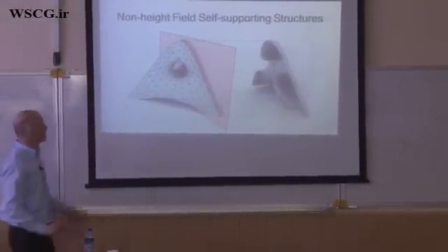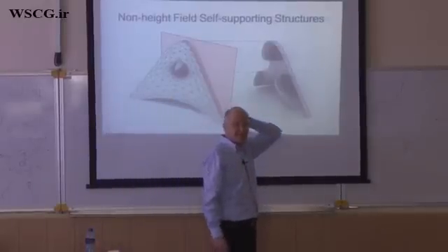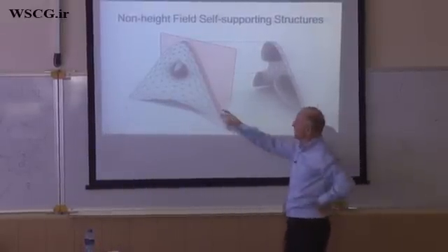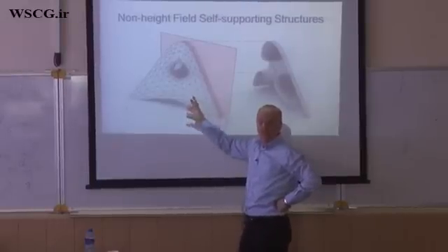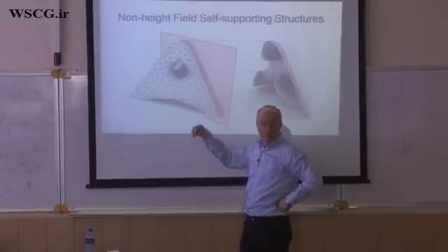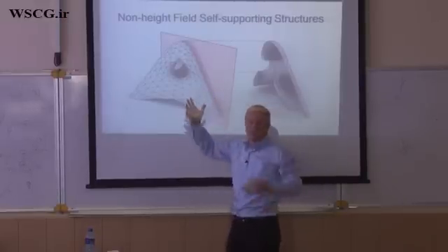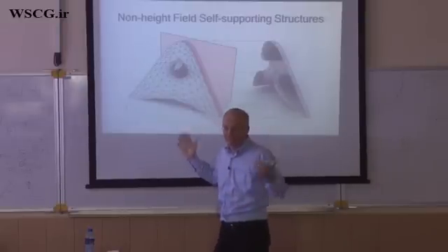What you see here is a triangle mesh, and this triangle mesh is a thrust network. It means you can assign forces in these edges of the mesh, which everywhere are in balance with the loads. And for the loads, of course, you have to assume some kind of material. I don't know with which weight it was computed.